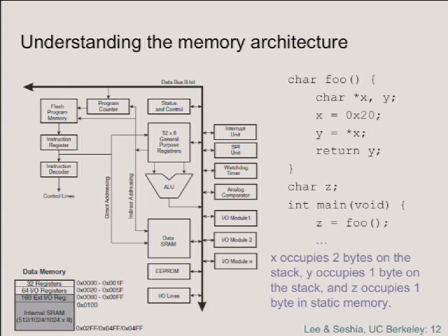So in a Harvard architecture, you would not store instructions in the data RAM. So you could be fetching 16-bit instructions in one cycle and 8-bit words in one cycle. If you have an instruction that has an immediate address in it, then it may take 2 cycles to execute that instruction because it may take two locations to store that instruction, right? If it's a 16-bit instruction word and it's a 16-bit address, then it takes 16 bits to store a single address. So the read immediate that specifies an address is going to take 2 instruction words to store, and so it'll take 2 cycles to fetch that.